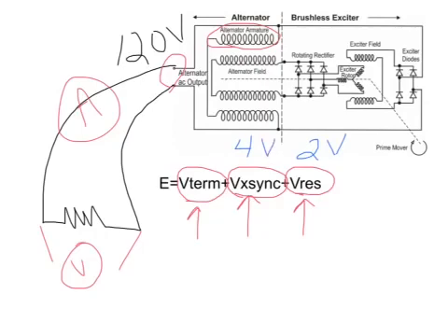If I was to maintain a full load output at 120 volts, assuming we're at full load with the load we have connected, I would have to produce a total of 126 volts in order to have 120 volts on my output.